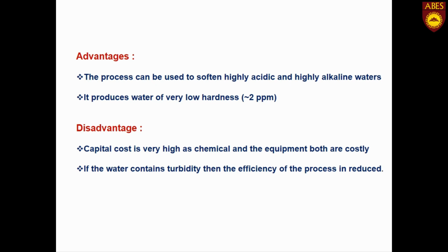On the other hand, the major disadvantage of this process is that it is very costly, because both the ion exchange resins as well as the equipment used are pretty costly. And also, if the water contains turbidity, then the efficiency of the process is reduced, because the micropores present inside the resins will be clogged by the particles.